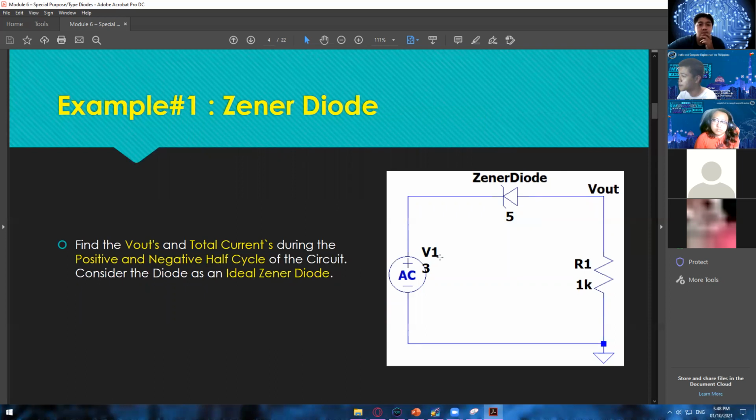Okay. So just imagine that this is like a voltage threshold, like in a forward bias. If it's non-ideal, it will eat 0.7 volts, right? But here, it requires a certain amount of voltage, which is 5 volts. Okay, the only difference is if this one is higher, then it will be able to pass through this diode, but it will not hit any voltage, or there is no voltage drop. Okay, so let's say if this one is 6 volts, we still have a reading here of 6 volts. That is their only difference.